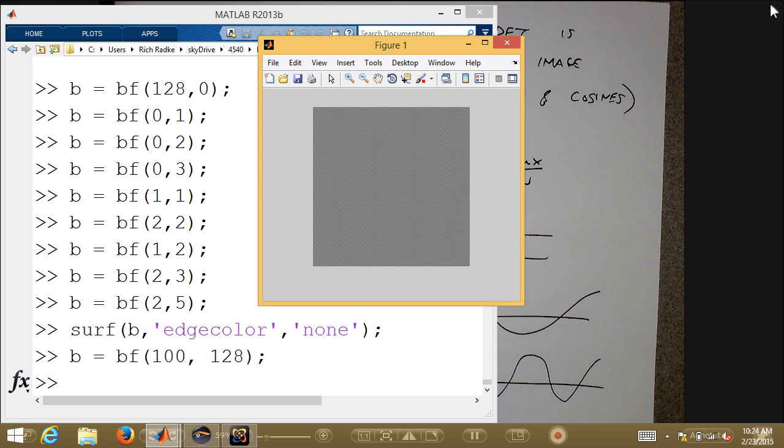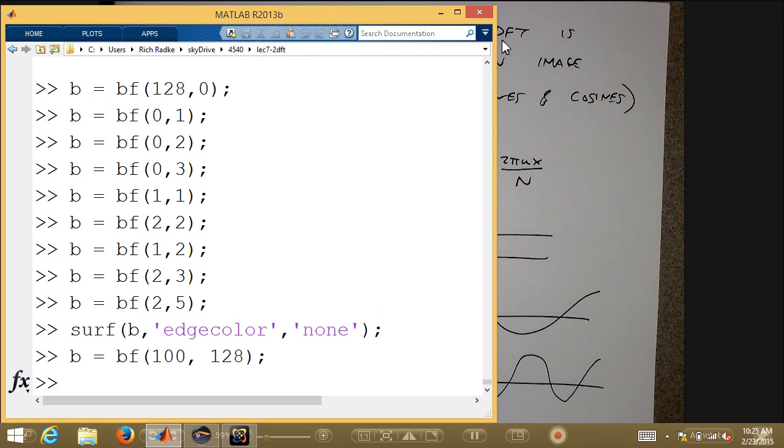So we're going to start to understand what things look like in the low frequency domain. Low frequency parts of the image are usually nice, big, flat, slowly varying regions, and high frequency parts of the image are edgy, noisy parts of the image. Just like if we wanted to remove staticky noise from an audio signal, we would low pass filter it. In the same way, if we had noise added to an image, we would low pass filter the image in 2 dimensions to get back a slightly better original image. We're going to talk about that more next time in terms of actually doing frequency domain filtering of images.